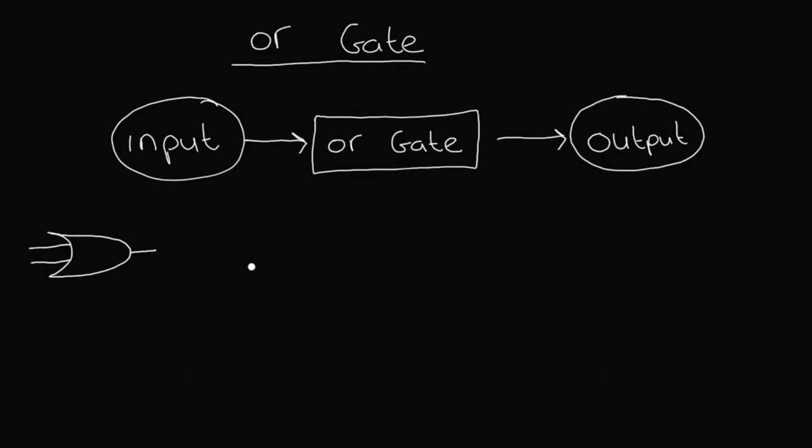And I think the easiest way to think about this OR gate is to look at two binary numbers. So let's imagine two of our binary numbers. The number 5 in binary is equal to 1, 0, 1, and we just put a 0 there at the beginning of it as well. You don't have to put a 0 if you don't want to. Then we're going to use an OR gate to get a result by ORing the number 5 and the number 1. So the number 1 in binary is 0, 0, 0, 1.